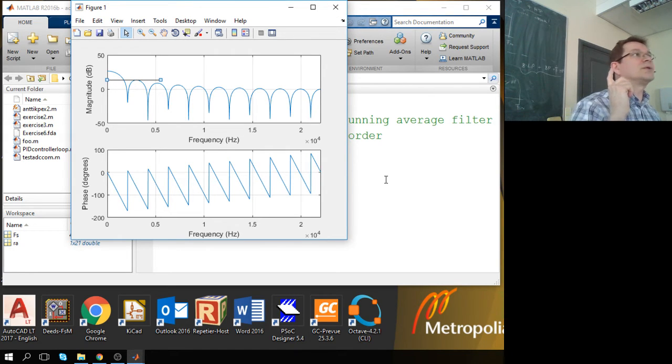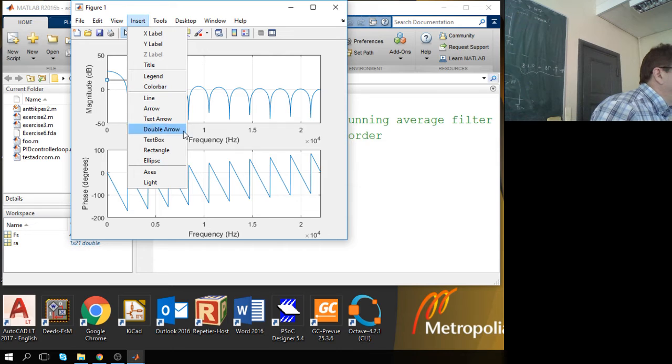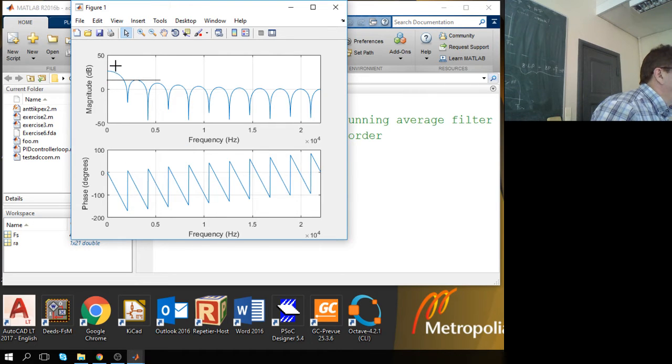So we can consider that as a window. First, I would like to check if I can make a cutoff frequency, which is defined somewhere in here. You have minus 3 dB points. Yeah, it has a nice cutoff frequency, but on the other hand, the stop band attenuation is not that great. But let's first fix the cutoff frequency, say up to 4 kilohertz, and use the sinc to do it.